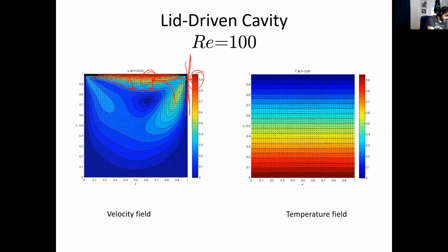So the flow is then deflected around the wall, downwards. There is no additional forcing of the flow anymore because the sidewall here is at rest. So that means there is no further acceleration of the flow. The boundary layer is not really growing anymore. The flow separates from the wall and then kind of goes back like this. So this is kind of what you would get.